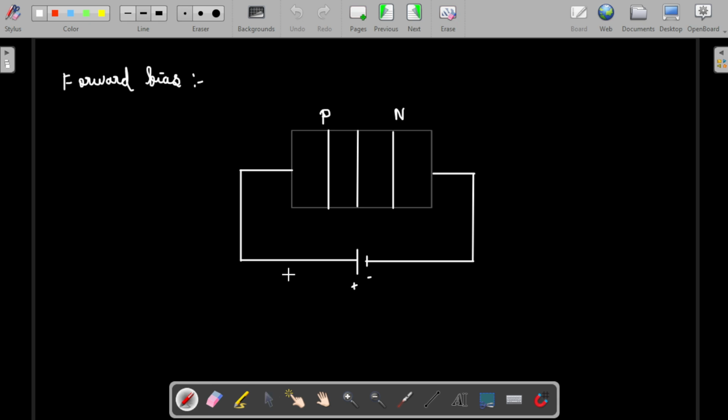So let me draw the charge carriers. Here it will be negative and holes will be present here. Here the holes will be removed as they will have diffused to this region before itself. Okay. So here, positive, as there are no holes, there won't be any holes, because there is a depletion region.